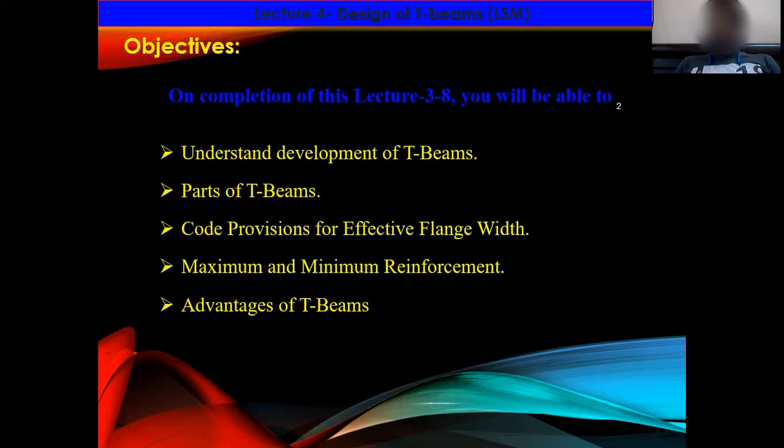And we will discuss what is meant by effective width of flange and how to determine for different conditions. And similarly, we will discuss about the maximum and minimum reinforcement required in design of T-beams. So these are the things you will be able to know after the completion of this lecture.